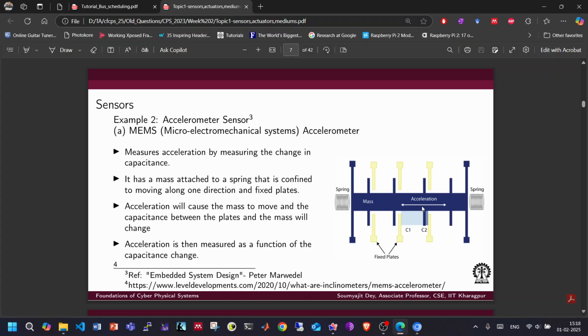So this is usually measured using the G scale. We know the G value is 9.8 meter per second square. So if we are calibrating with 1G, then it means that I am having an acceleration of 9.8 meter per second square. With 2G or 1.5G, accordingly it increases or decreases. So basically it gives me an output with respect to the G value.